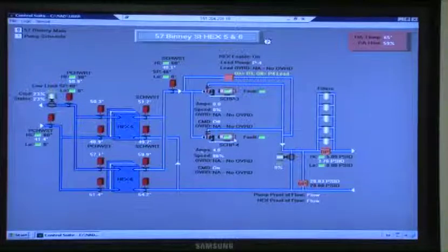Then we come down here, now we got pumps. Are these on schedules? Yes, they'll rotate on the schedule that Jamie has set up. And we have overrides if we need to command them on and off, it overrides them. We have 2 pumps. This pump is on, overrideable there. And then we have this valve here maintaining, the same from the other graphic, just a little different.